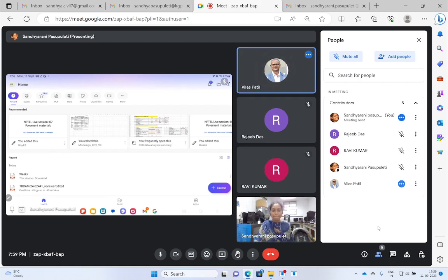And one more thing: we are using sulfur as a cross-linking agent. So it helps to improve the storage stability. When it is added to the base binder, it will make the polymer disperse sufficiently. If you don't add that sulfur, the maltene fraction and the asphaltene, their dispersion will completely collapse. So to maintain that stability in storage, we need to add the cross-linking agent, sulfur. Okay, thank you, madam.